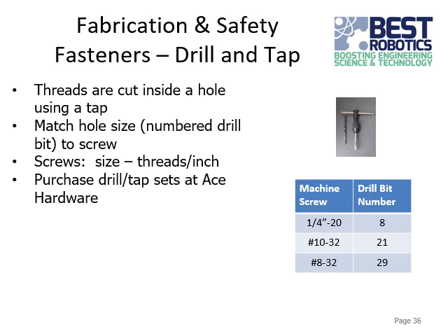Just make sure when you are tapping it, you can kind of see it in that picture on the right, it's a little T-shaped part. A lot of times you'll need to go in a little bit and then back it back out, so that it can remove the bits of metal that are cutting out as it goes along. Otherwise, that metal can fall into the bottom of the hole, or get stuck in the cutting surfaces, and then mess up your threads. Also sometimes it's good to use cutting fluid to keep the tap cutting surfaces sharp and all that.